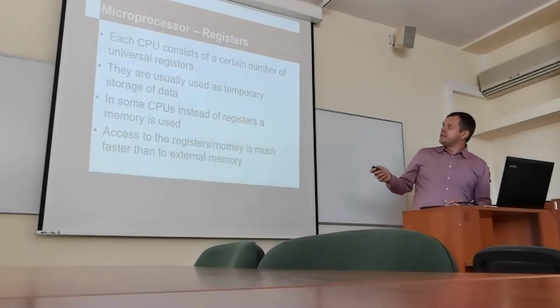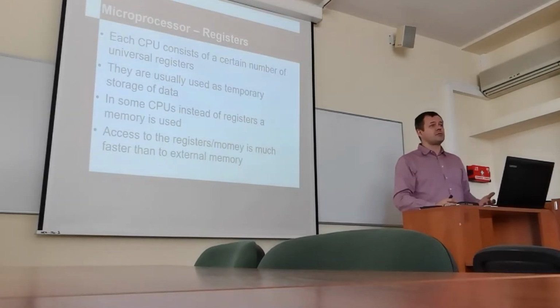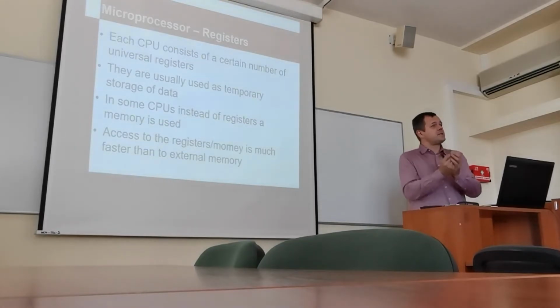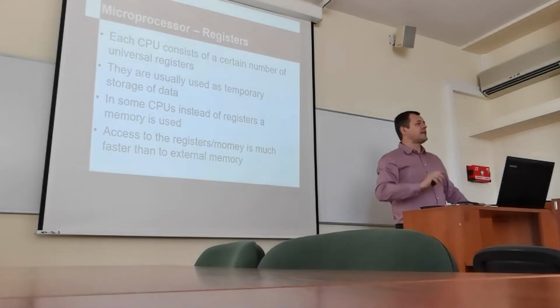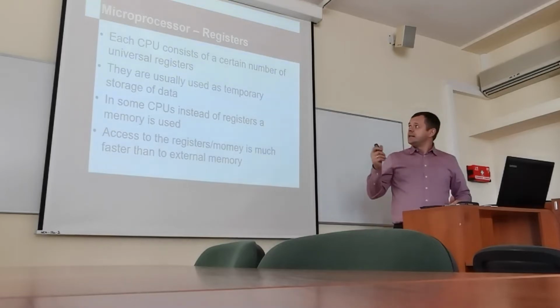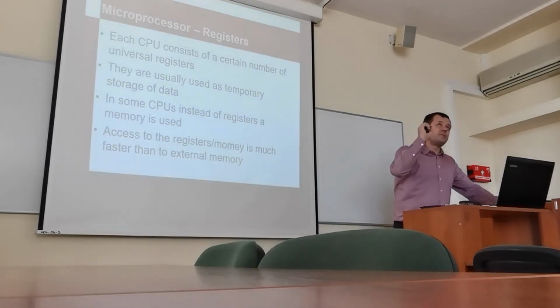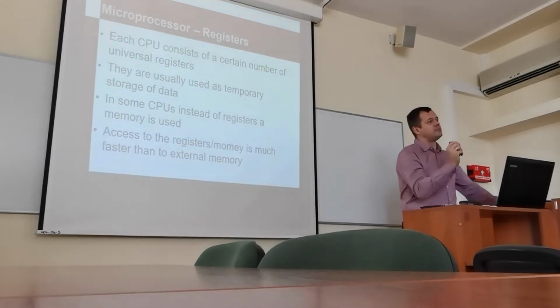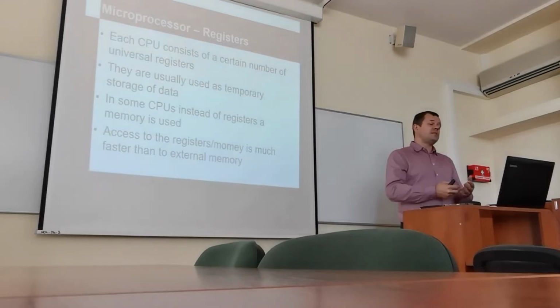The difference is that the registers are the same kind of memory as the stack pointer. In some microcontrollers, it's physically the same silicon. Completely physically the same silicon, just different addresses, so different areas of the same silicon in some microcontrollers. The registers and the static memory where the stack pointer is hidden. But what is special about the registers is that they are specially available. So they are treated specially. So they are available in addressing modes, in short addressing modes.